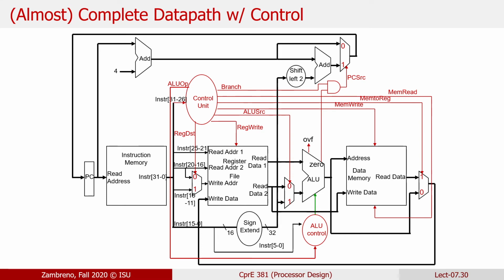And again, we talked about the naming convention enough. For your design, I'm not telling you you need this signal to be a 0. It depends on your mux. It depends on what you name that control signal, what 1 corresponds to, and it depends on what order you connected the inputs to your mux.